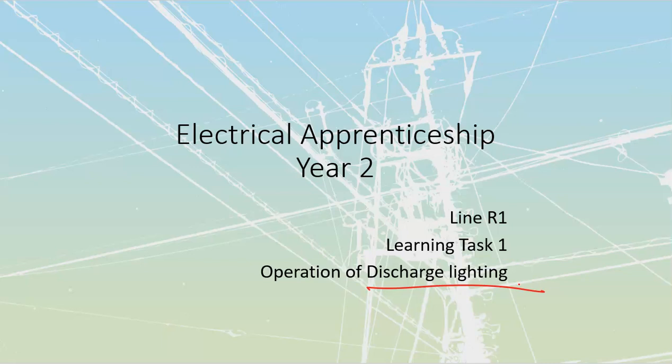Discharge lighting just refers to the discharge of ultraviolet radiation that's caused by collisions between electrons and mercury. We're going to take that UV radiation and safely convert it into visible light waves. All we're doing is shifting the frequency that it's going to be operating at.